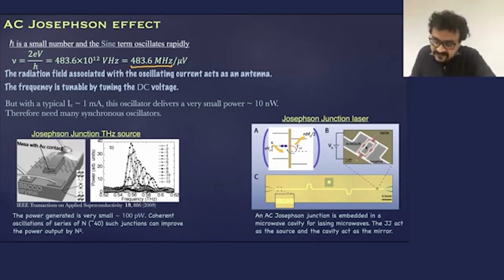So this long conductor that you are seeing here in the center has basically a capacitance gap here on either side, okay. And you have a Josephson junction. Now this mirror, or this is actually a resonator, a superconducting microwave resonator which is tuned to this frequency, and this actually can capture the radiation emitted by the Josephson junction, and the Josephson junction can capture this radiation back.